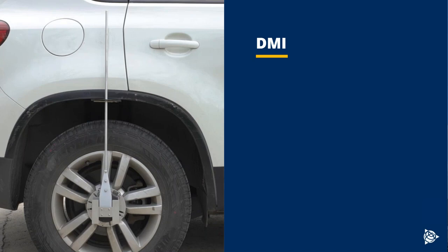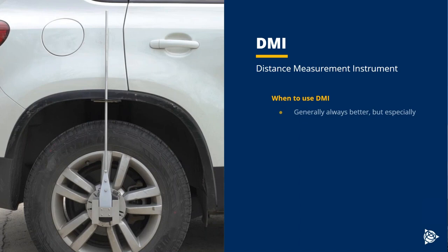All right. Then quickly about the DMI before we go to the lever arms. DMI is a distance measurement instrument or indicator. It's a device you see on the left side. It's attached to the rear wheel of the car. So it's measuring the rotation of the wheel, giving us accurate distance and accurate velocity. When would you use DMI? Generally, we would say that it's always good to use it. It's never a bad thing to use it, but especially with a couple of different scenarios.